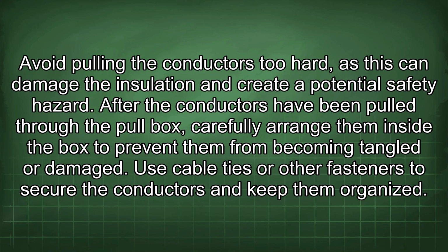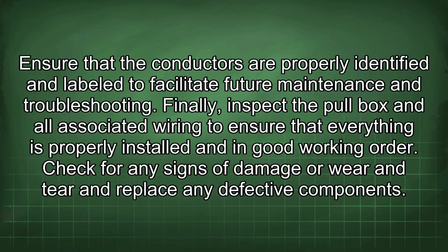After the conductors have been pulled through the pull box, carefully arrange them inside the box to prevent them from becoming tangled or damaged. Use cable ties or other fasteners to secure the conductors and keep them organized. Ensure that the conductors are properly identified and labeled to facilitate future maintenance and troubleshooting.